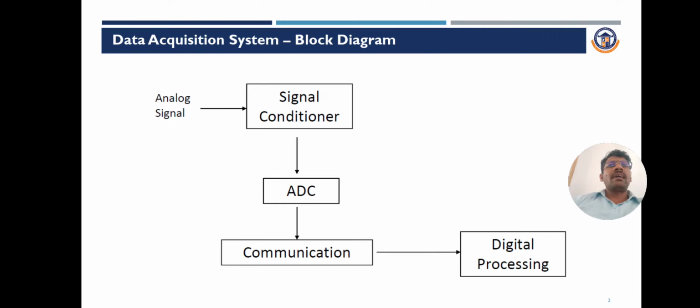Data acquisition plug-in boards are general purpose data acquisition instruments suited for measuring voltage signals. In the real world, the sensors and transducers give an output signal that must be conditioned before the data acquisition board can effectively and accurately acquire it.